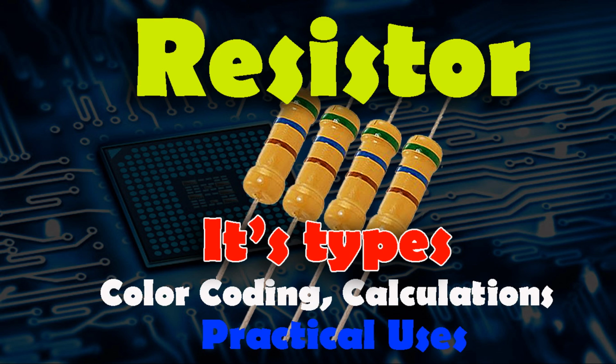Collector-to-base bias. Description. A resistor is connected between the collector and the base. This configuration provides negative feedback, which stabilizes the operating point. Advantages. More stable than fixed bias. Disadvantages. Limited by the variation in collector current due to transistor parameter changes. Voltage divider bias. Description.